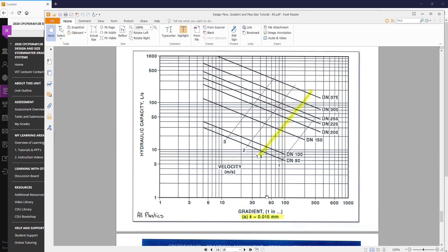The minimum grade that we can get for 90 mil pipe, and we go up here, there's 2 there, so we go straight up. So where 90 goes below 1.5, because our litres per second is lower than where 90 goes through here, because we're at 1.2, the minimum size pipe's 90, so we have to go up to 90. Where it's just below, right, we can't go to 1:40 because that's above 1.5. So we have to stay below 1.5.